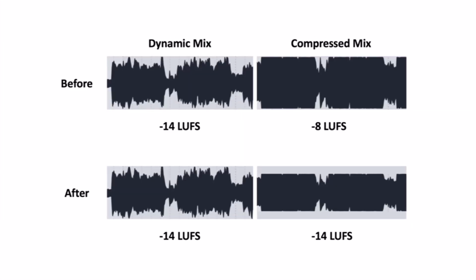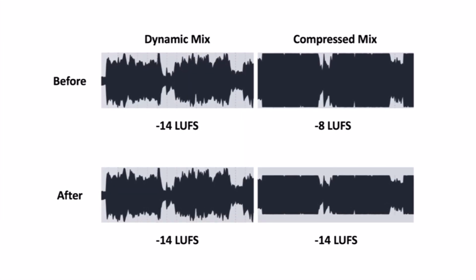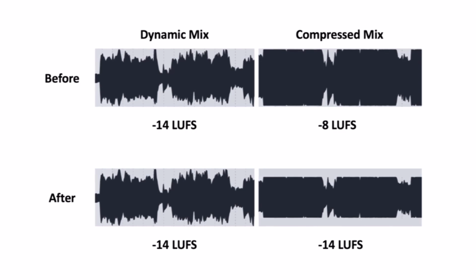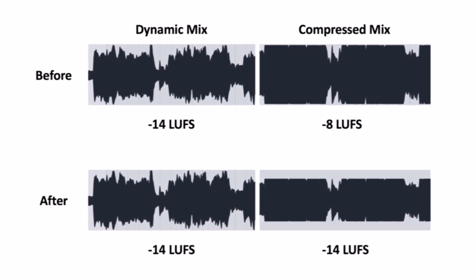It's something that we look for in all kinds of music equipment, whether we're consciously going for that or not. Because if we just listen to a raw guitar signal, it would be pretty unwieldy in a lot of the genres we use it for. In that prior example of the mix engineer using a clipper plugin to make a mix louder, that is essentially altering the dynamic range. You are making the mix spend more time at that threshold and thereby being louder all the time. Now, it's not the same as rounding out the signal like a limiter or a compressor would, and once it gets translated into the analog domain, you hear some interesting results of that.